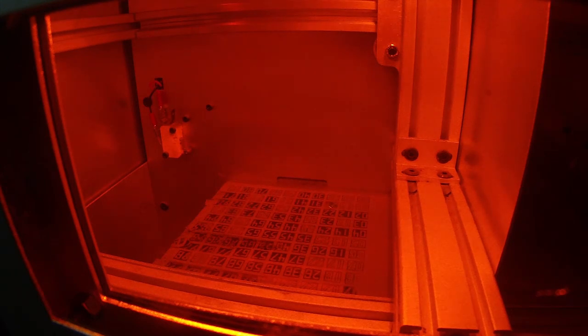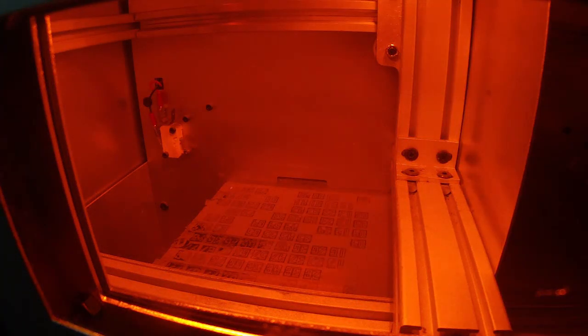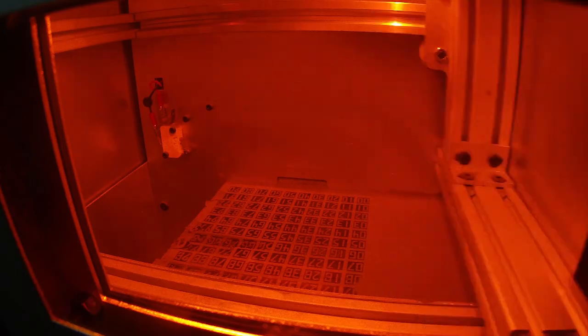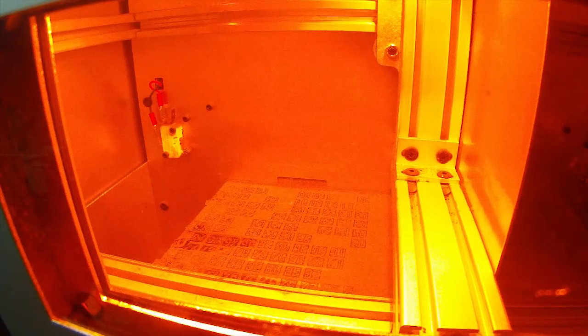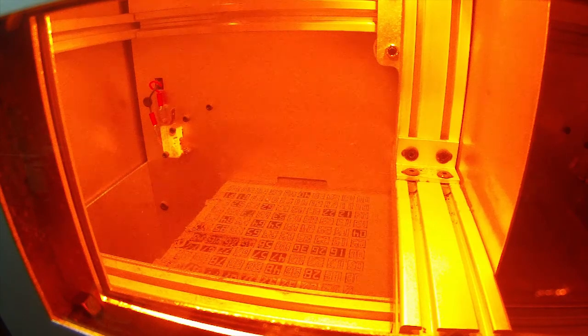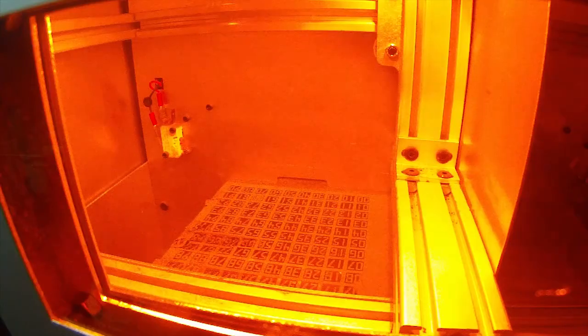And you're probably wondering, why isn't it applying powder to the whole thing? Well, even the slightest depression in the bed, on the left side bed, will fill up, and then the powder won't flow all the way to the outside, all the way to the overflow bin, because it still has to keep refilling it. Eventually it will refill it, as you can see in the video. It's gradually working in there because I bumped it up to 173.9 at this point, and all that was curling now were the corner pieces.